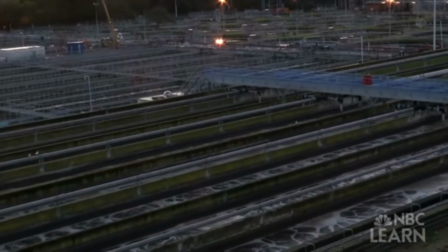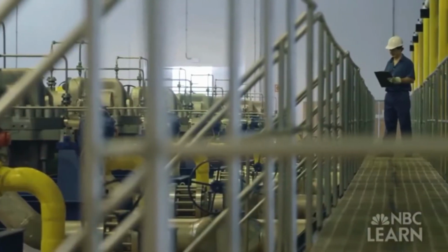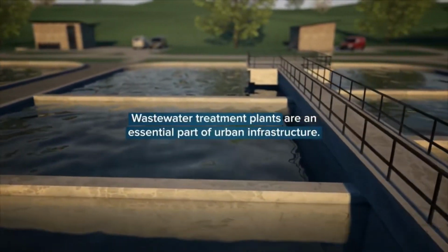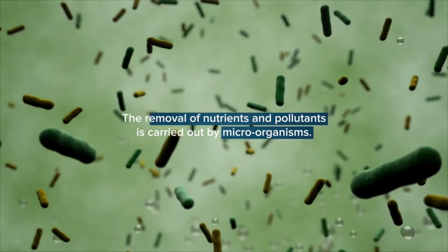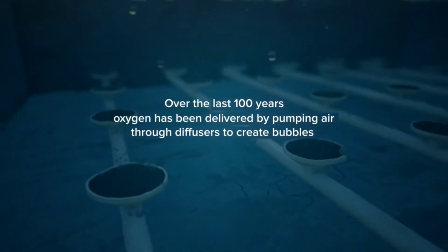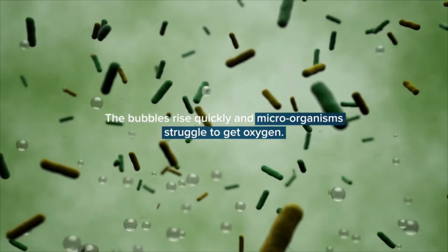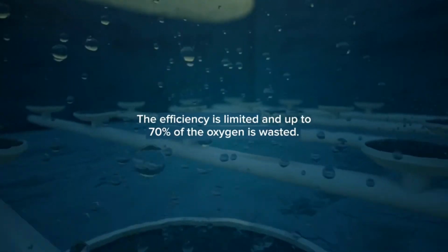Wastewater treatment systems are designed to treat water so it can be recycled safely back into the environment. But that doesn't mean wastewater treatment plants aren't faced with their own issues. Up to 60% of the energy used by wastewater treatment plant is dedicated solely to the aeration process that controls the degradation of organic matter. To save the energy used, my recommendation for innovation of current system is using membrane aerated biofilm reactor. In this part of the video, I'm going to show why I recommend this technology.